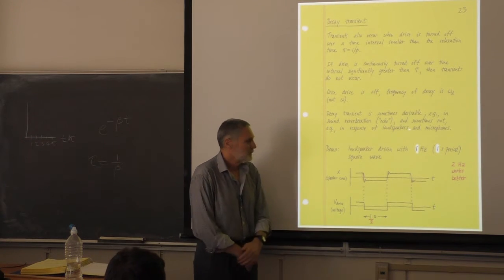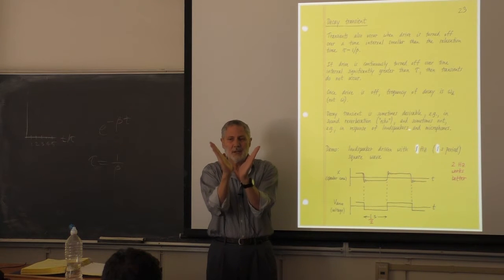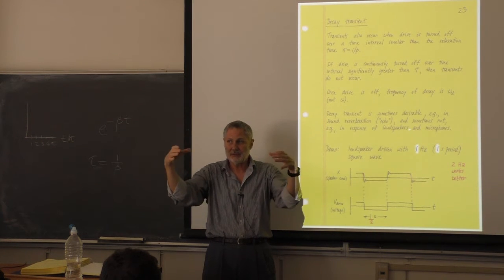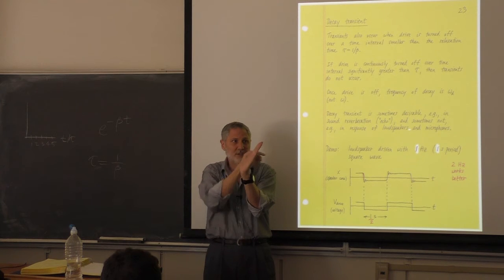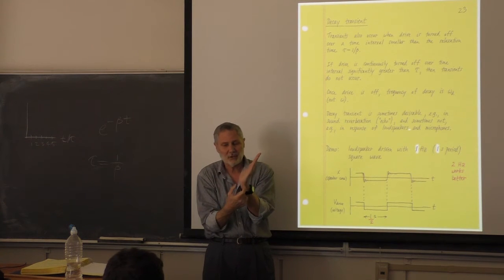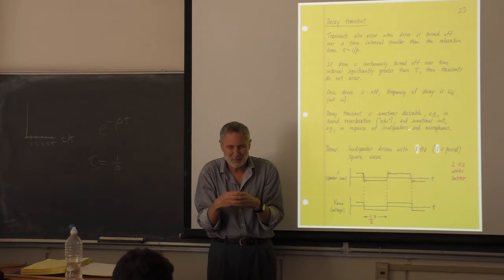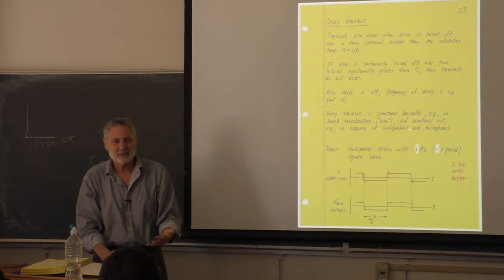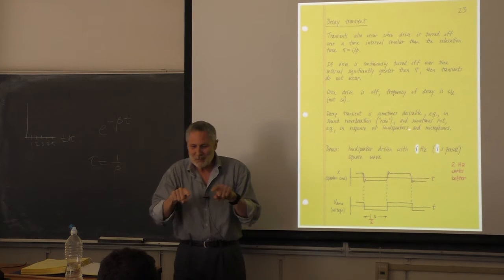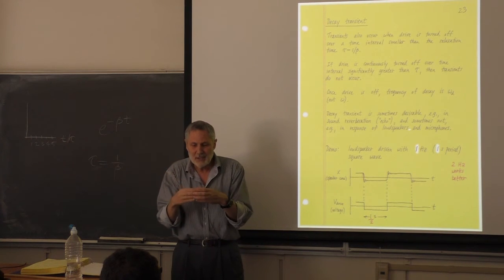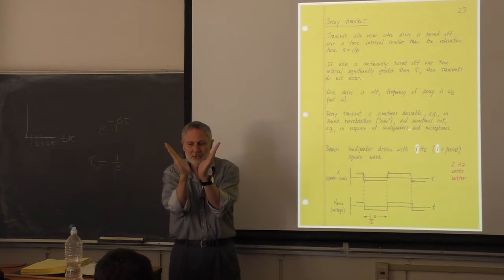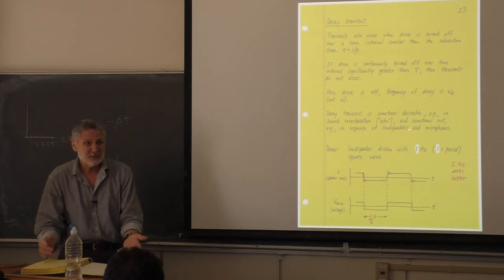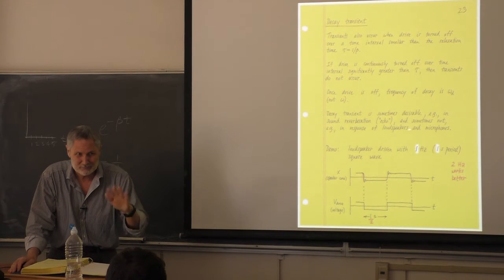But one more thing I've got to tell you. This cone is just not free here. There's what's called a surround here that anchors it to the frame. So when this goes up like this, there's a restoring force due to the surround. You've also got to keep the voice coil centered in the magnetic gap, or it'll rub. So there's what's called a spider, and it's universally brown. I don't know why that is. But maybe you've seen it. It looks kind of like this. It's this corrugated type thing. When the cone moves up and the voice coil moves up, that also supplies some restoring force. So we have a restoring force that approximately obeys Hooke's law over some range of amplitudes.